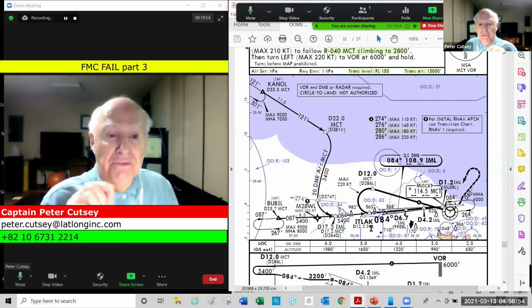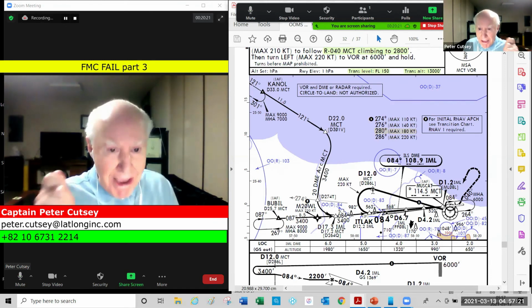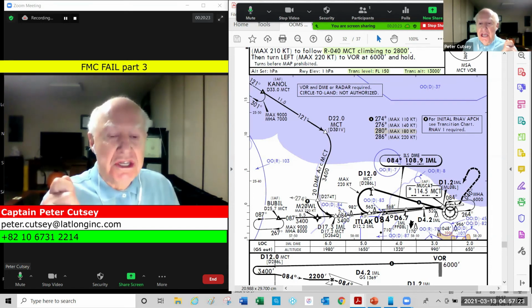The pilot flying is focusing on looking at the DME and not going beyond, let's say, 15 DME. You're in a turn, you want a reasonable rate of turn. You don't have LNAV, but if you're going to use 20 degrees of bank, depending on the wind, that's a good starter to use, somewhere between 15 and 20. And why? It's all mathematics, and I'll explain that someday, but you don't want to get involved in that. Just fly the airplane and look at the DME as you're flying the airplane, and then roll out on a